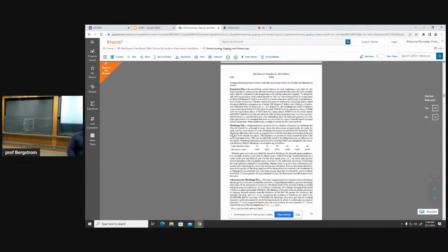So once you put it together like that, how do you take it apart? Yeah, bigger hammer is the only way, right? You have to break it. So those are really good for permanent things. So we got running sliding fits. Running sliding fit is when you want it to go in and come out easily. A press fit is when you want to have to use force to push it together. And so if you go to the Machinery's Handbook and look for the allowances for tolerances and fits, if you know what size either the hole or the shaft is, you can then dimension the other part and put the correct tolerances on it so that it works every time.